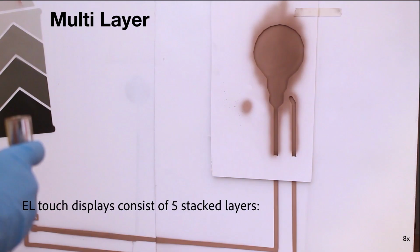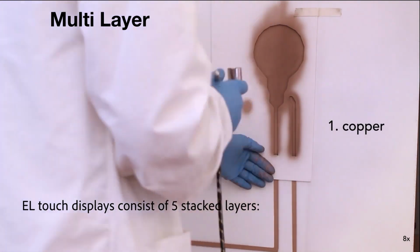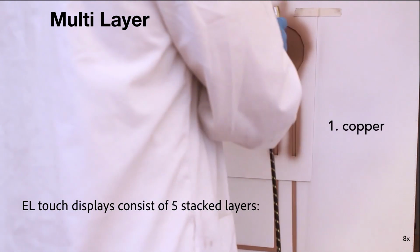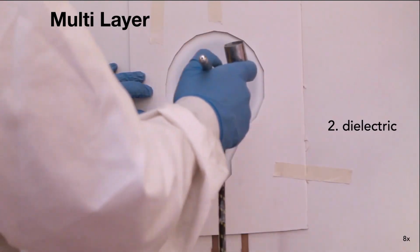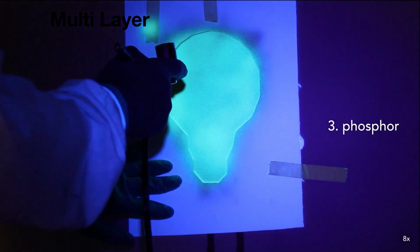Good, so how does the multi-layer fabrication look, and how can we make electroluminescent touch displays with this approach? So here you can see how spraying a display looks. We first start with one layer of conductive copper that you spray in a specific shape, here supported with some fabricated stencils. Then you add a dielectric layer, a light-emitting phosphor layer.